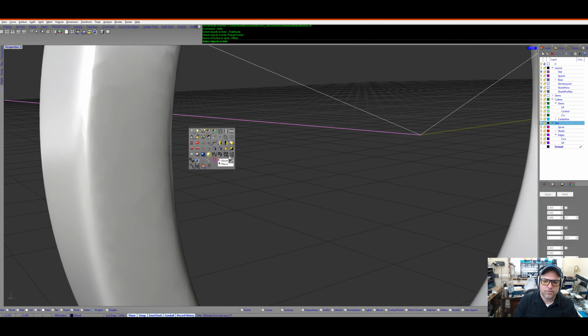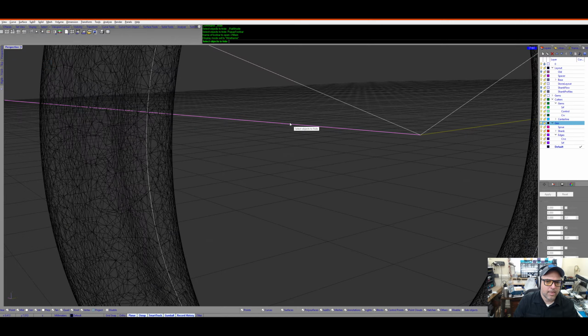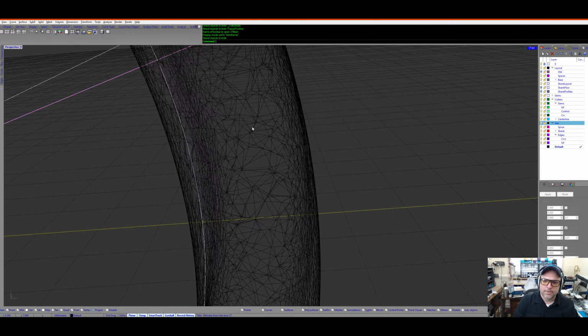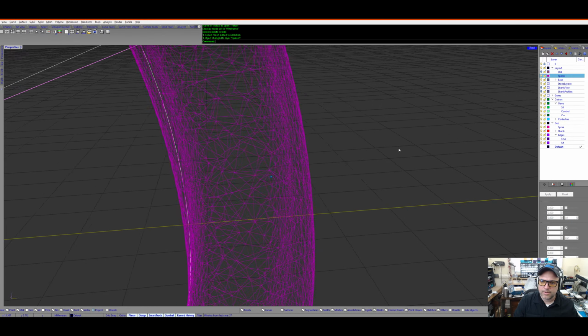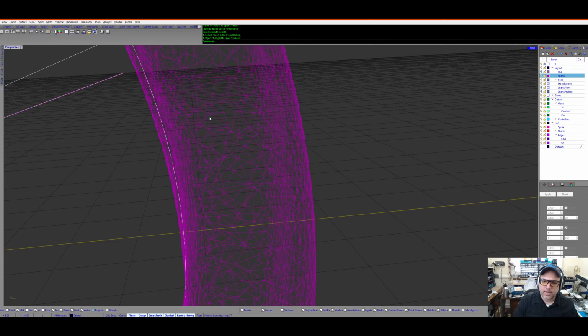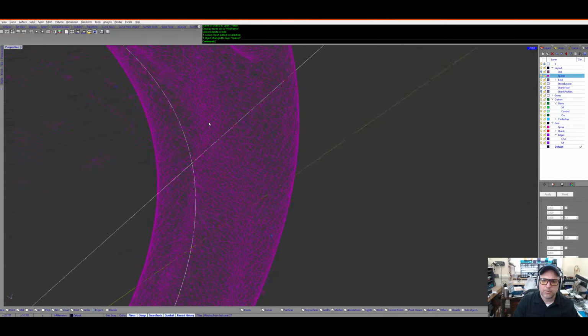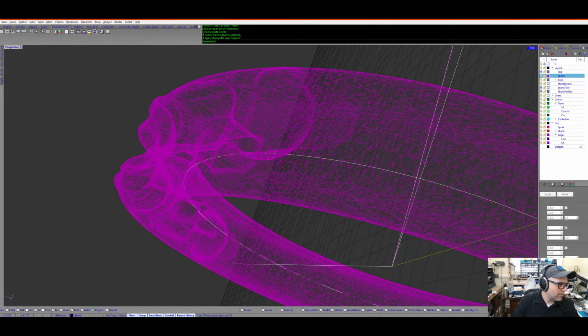Oh, we can actually just go to wireframe because we're in Rhino. Wireframe. I don't have a button for wireframe. Where is it? I never use it. Okay. And now you can see the triangles a little bit better. Let me move this to a different layer so it changes the color. Now you can see that we've got medium-sized triangles, tiny sized triangles. Everywhere we have curvature, that is more than enough detail for our thing.